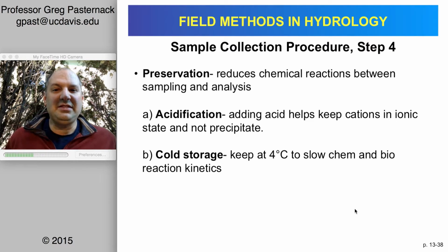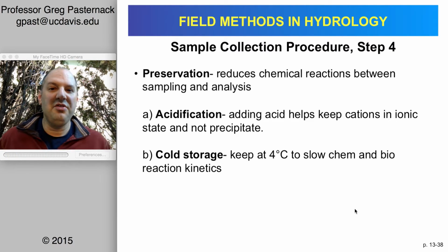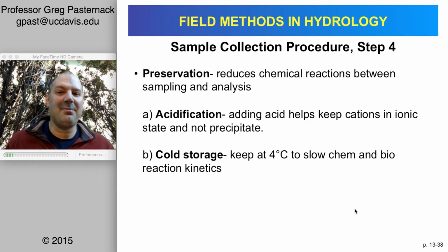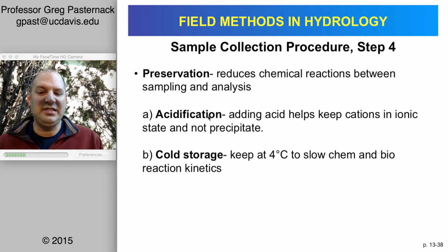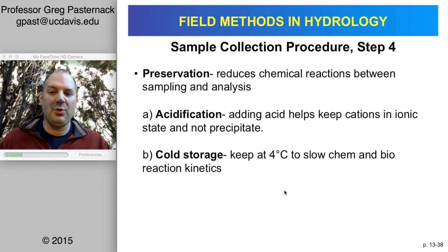It also may be necessary to preserve a sample. That can be done to prevent chemical reactions, precipitation specifically, as well as to reduce the rate of chemical reactions and biological processes. So typically that's done through acidification and cold storage.